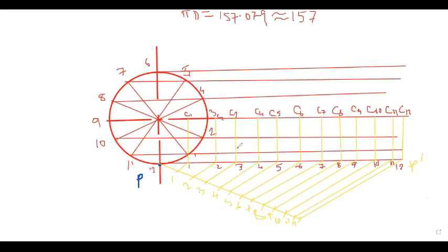Yeah. Now take this radius from this center point, first center point C1, and see where it cuts the horizontal line. Suppose it will cut here. Your radius will be 25 millimeters. So take this radius at center point C1. In the horizontal line of C1, where will it cut? It will cut here. Then center point C2, where will it cut? Suppose it cuts here.